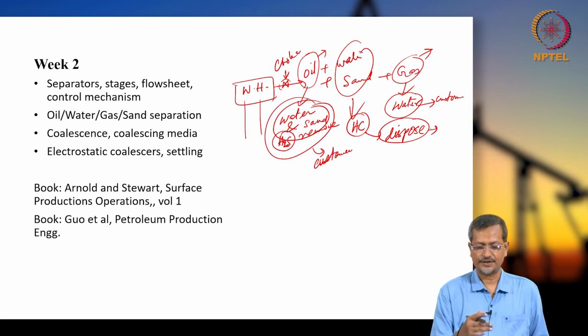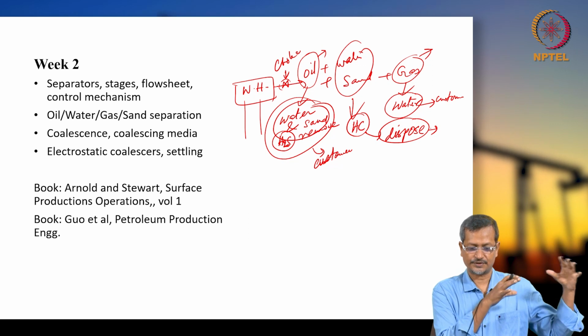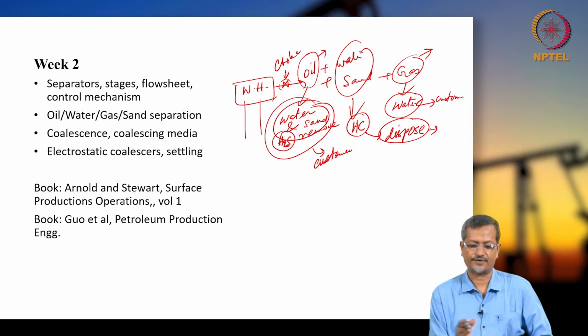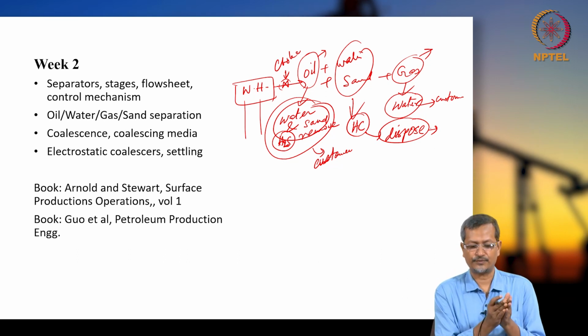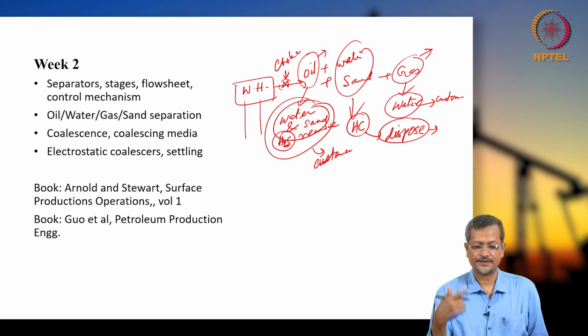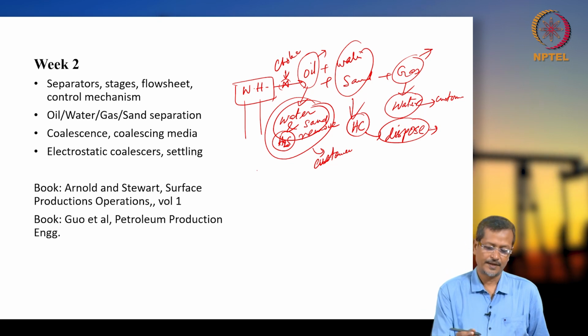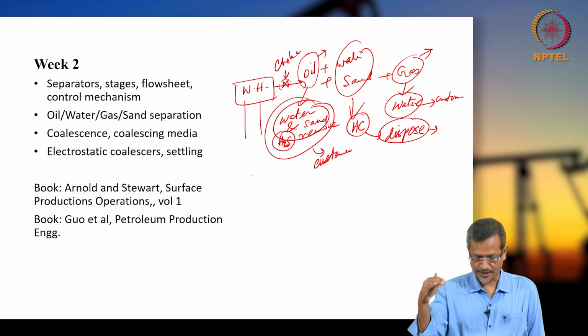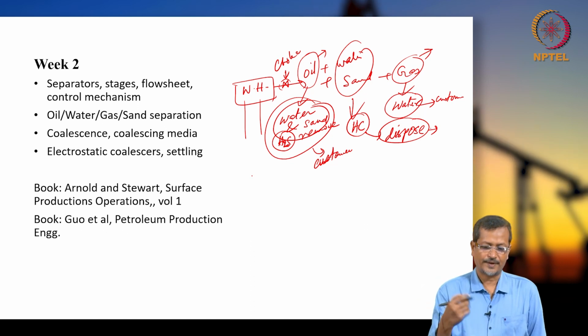After the choke, the pressure will be something different. So you get reduced pressure. When you get reduced pressure, it is possible that the temperature will also go down because the PV equals nRT formula is there. So if you are reducing pressure, temperature also can go down, volume can increase.